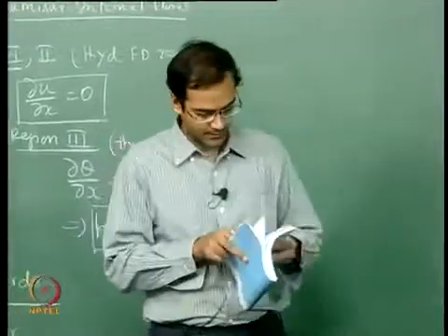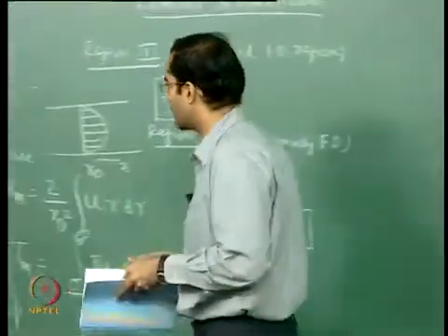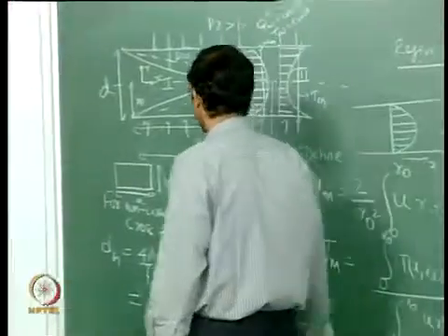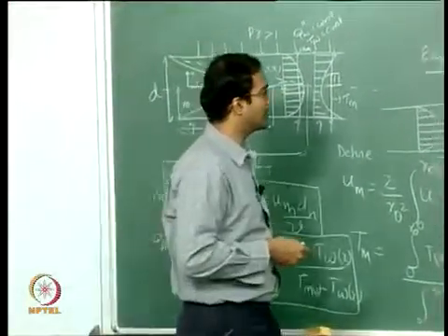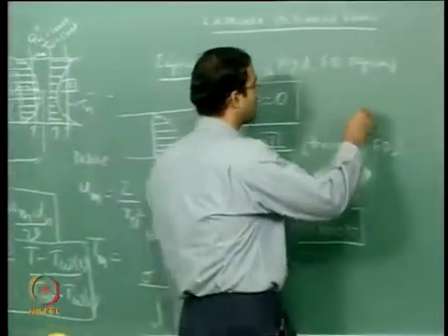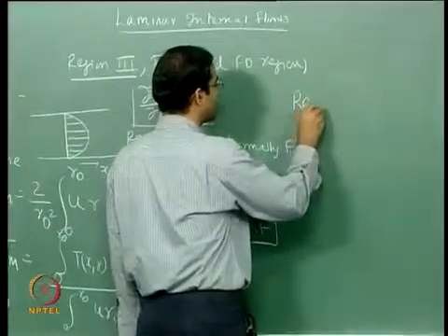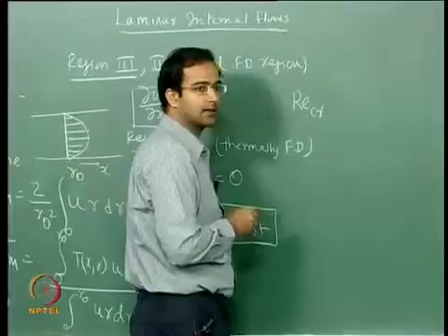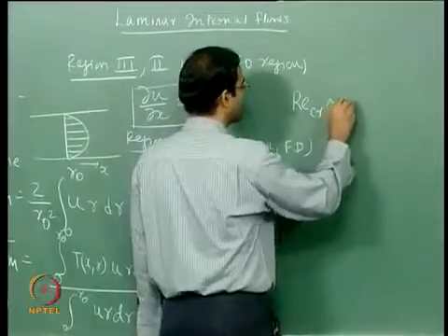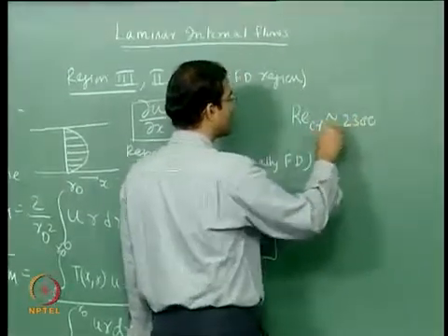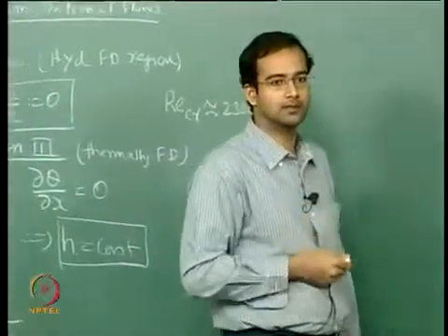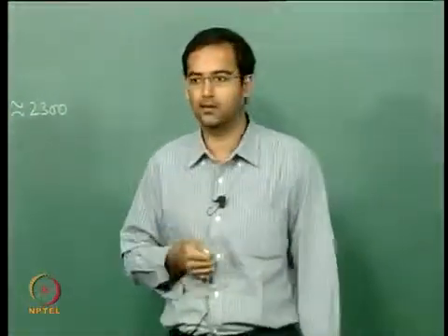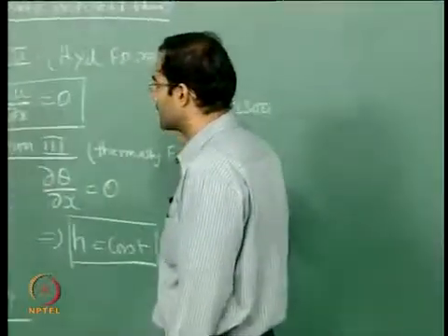So now, with sufficient understanding, we have also classified the different regimes, whether it is laminar or turbulent, depending on the value of Reynolds number. Critical Reynolds number generally is about 2300. So below this value it is generally classified as laminar flow, and above this it is generally considered as transition or turbulent, although this value may vary.